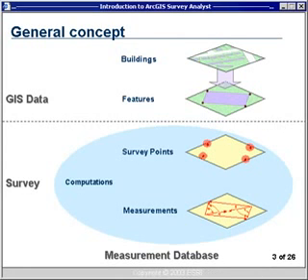Now what we have is the survey points and GIS coordinates associated with those points. The purpose of this is to select those same features in my GIS layer, such as those building corners, and then perform an operation of linking, where we select an individual feature, link it to the survey point, and then we can perform operations such as adjusting, snapping that feature to its new surveyed location.